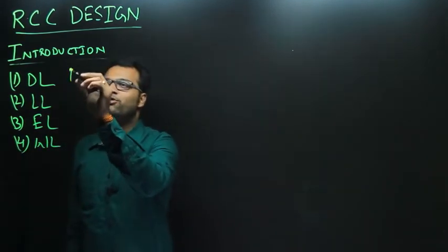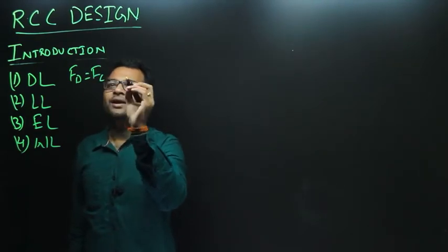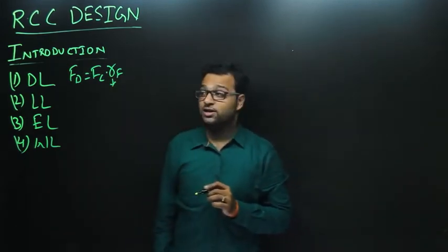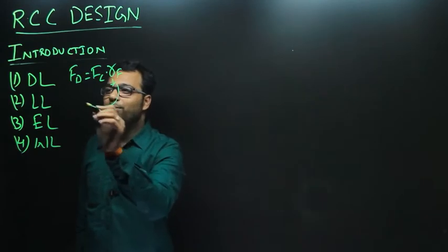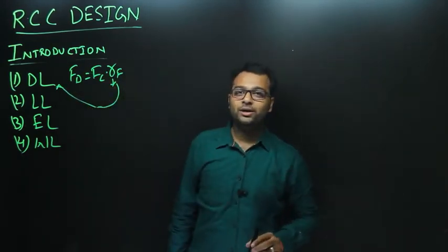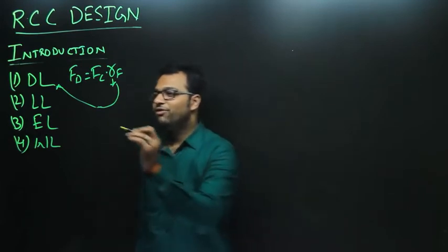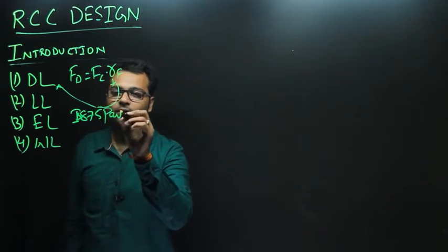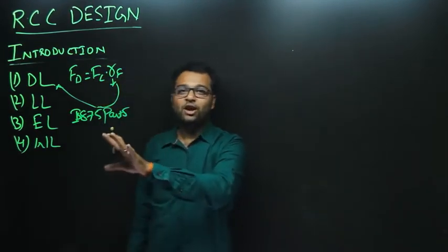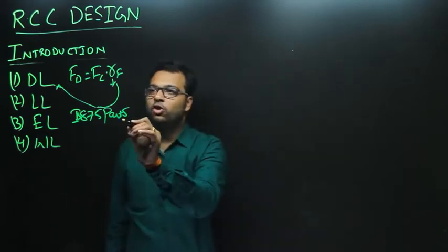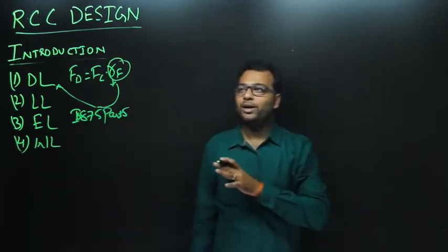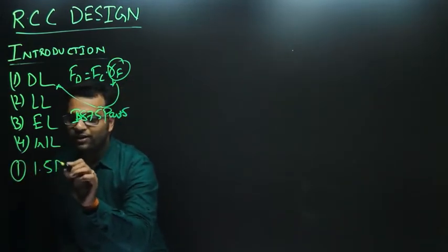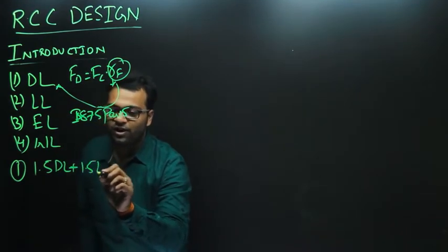Remember when I said that the design force is calculated by Fc multiplied by gamma F. This is the partial safety factor for loads. These factors are applied with these loads in the load combinations, and the load combinations are given in IS 875 part 5. I'll just list down some of the combinations, not the entire list, just to give an idea what kind of factor we can expect. The first load combination can be 1.5 dead load plus 1.5 live load.